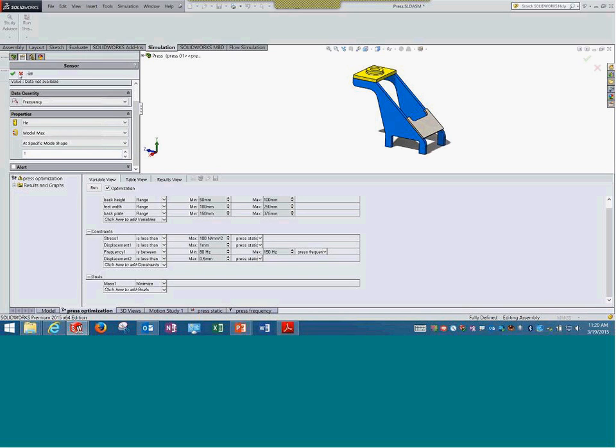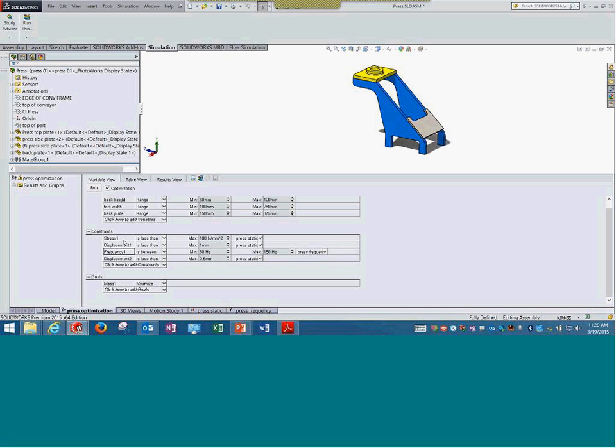So now if you see here, one is rest. Over here in terms of constraint, it's as simple as you just want to monitor. You want to see the variation of that value, and that would be similar to what we saw in design insight. Other options are monitor only, is greater than, is less than, or is between. Is greater than: the stress should always be more than, say, a certain value in Pascals, etc. So those can be specified here.